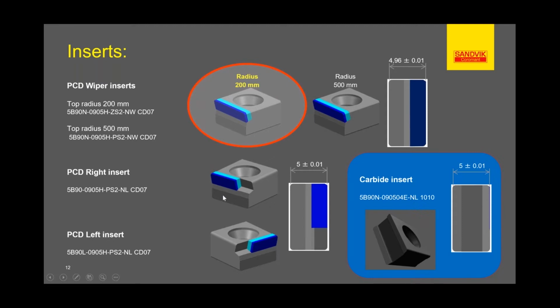That being said, we do have standard inserts for the other pockets, 1 through 9, and then you would put the wiper insert up here in pocket number 10, okay? But why have the confusion? The price of the inserts is the same, so it's not like it's a savings to go with these. So in most cases, it works just fine to put in that wiper in every pocket.